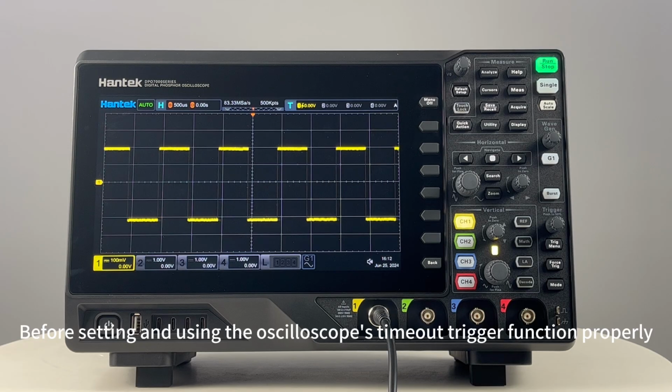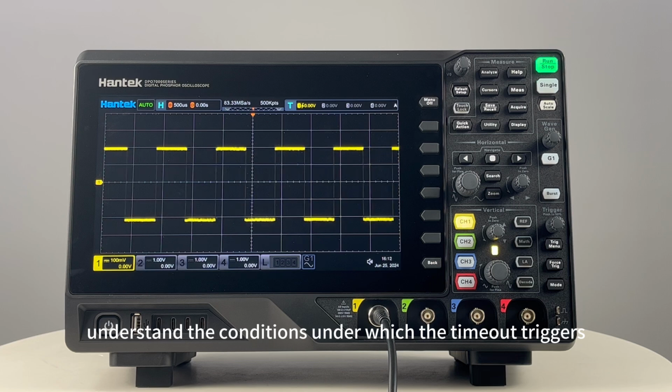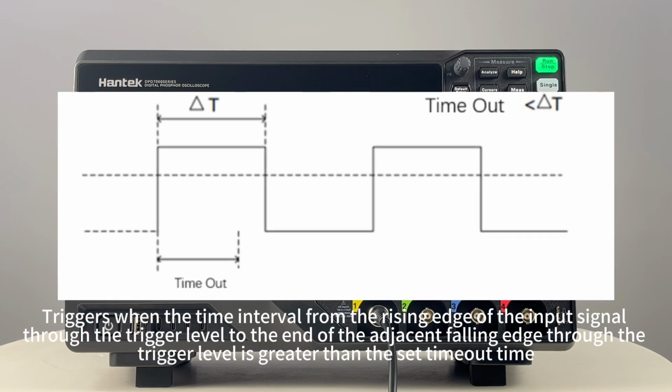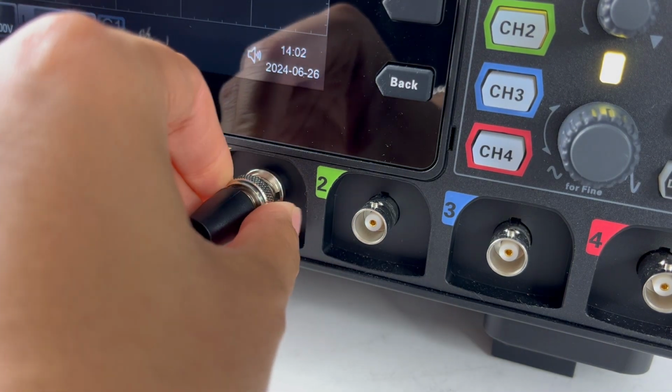Before setting and using the oscilloscope's timeout trigger function properly, understand the conditions under which the timeout triggers: when the time interval from the rising edge of the input signal through the trigger level to the end of the adjacent falling edge through the trigger level is greater than the set timeout time. We connected the measured signal to the oscilloscope.